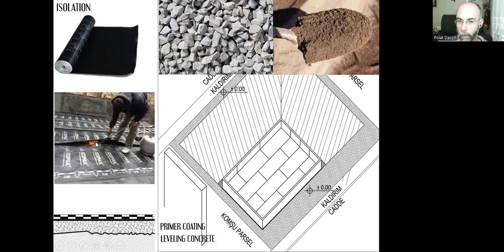By using a blowtorch, we can apply two layers of bitumen sheets. As you can see, they will be overlapping the first layer, and the second layer will be in the middle part. These joints will coincide with the middle parts. There will be two layers of membrane, and we need to protect that water insulation because workers will be walking over that water insulation, and they can drop certain things. The water membranes can be damaged, so we need protection.